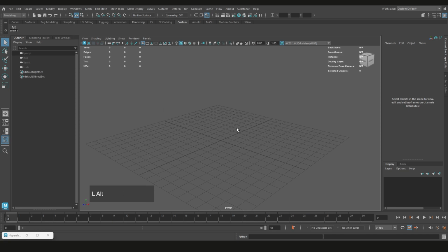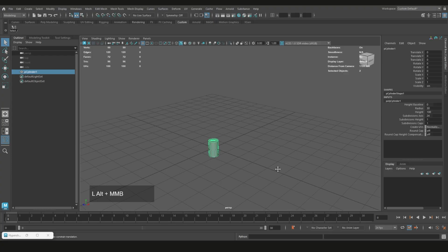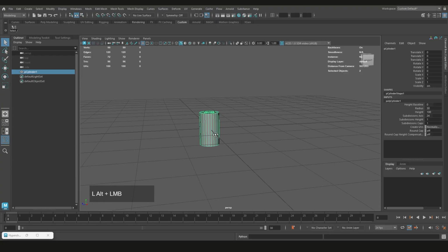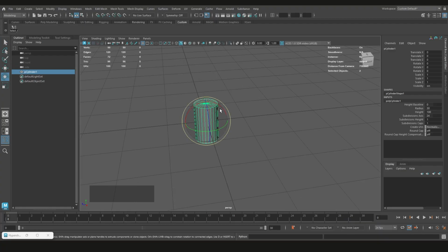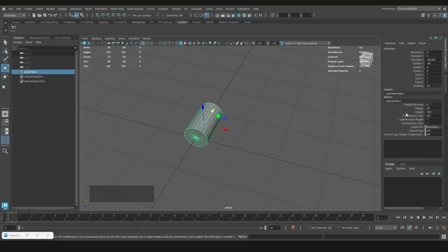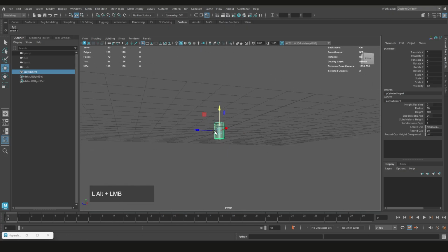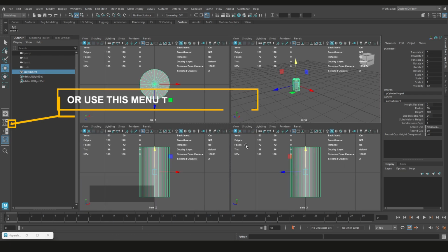So there we go. And to check that, we'll hold down Shift, right click and drag to a cylinder. And the cool thing here is that you can change a bunch of things. So if we have the height at 100, we can just do this and see, okay, does that actually work? So there, W, right? And we know, yeah, that works out because that's 100. And that there is 100, so that works out. And if you're really paranoid, you can tap spacebar. You might have this by default, so if you just tap spacebar, this will go into the view there.